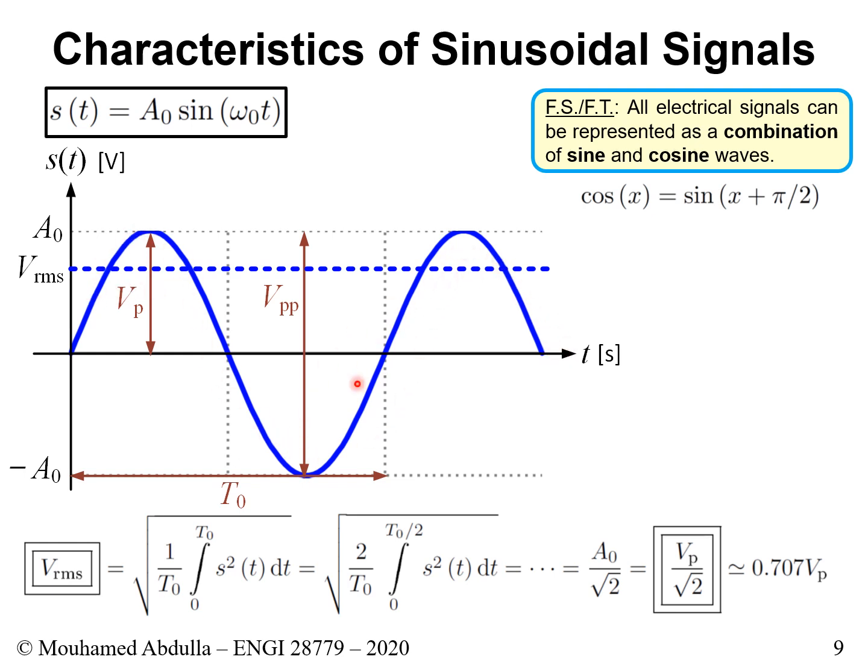And if you want to see the same effect of the signal, but instead of having an AC type of signal, you want a battery equivalent of it. What would the voltage be if you were to represent this AC signal in a battery equivalent? This is what RMS is, VRMS. RMS stands for root mean square, and it is this equation here.